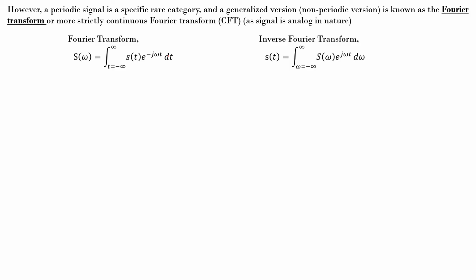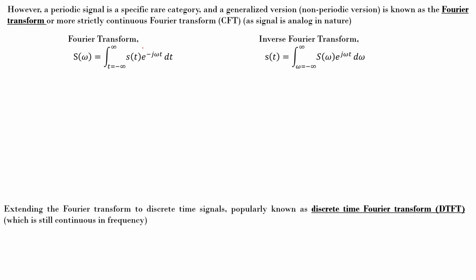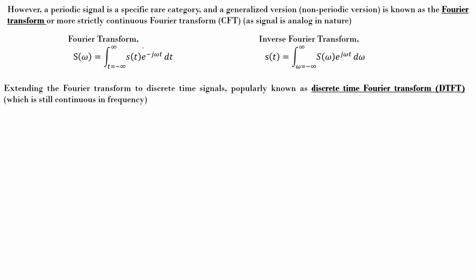Now there is a problem again here. This is continuous time, and imagine that you are implementing a Fourier transform in an analog system. It's almost impossible to do, right? So you need to go to a digital system, and you should not worry much, because there definitely exists something known as the discrete Fourier transform, or the discrete time Fourier transform to start with. Why discrete time Fourier transform? Because now t is no more continuous. I am going to discretize my t. So t will be something like nTs, where n is a number and Ts is the sampling interval. So what does all this mean?